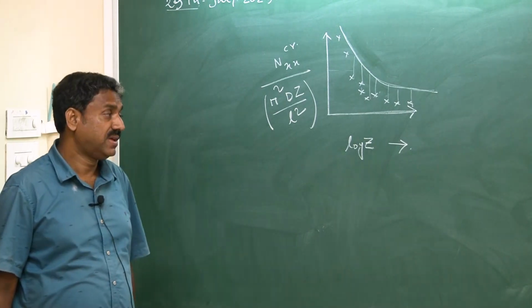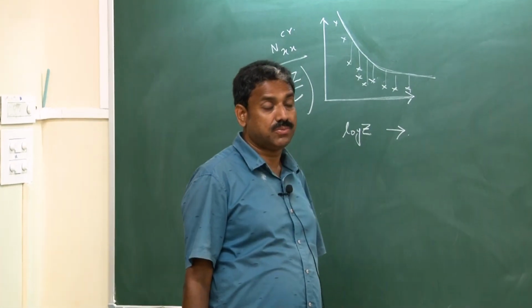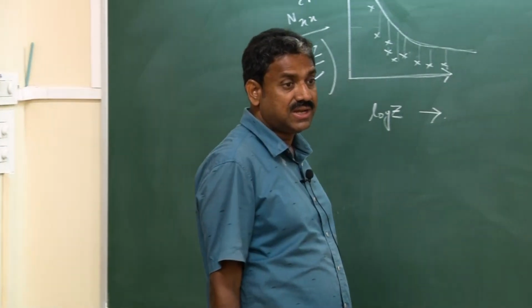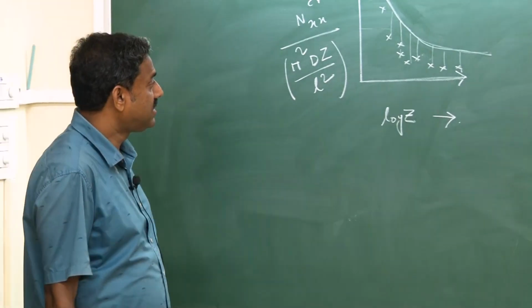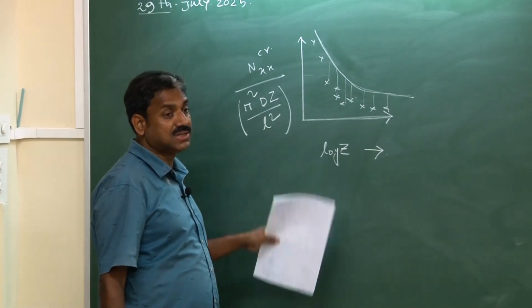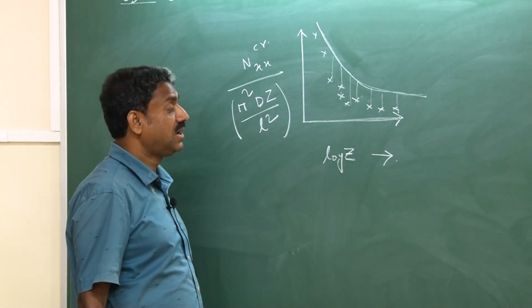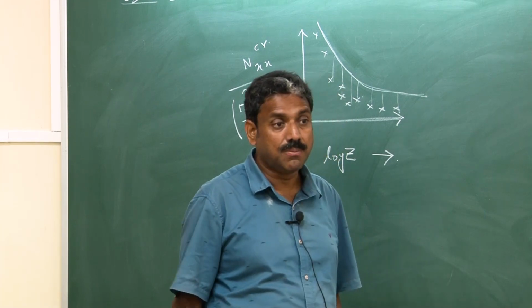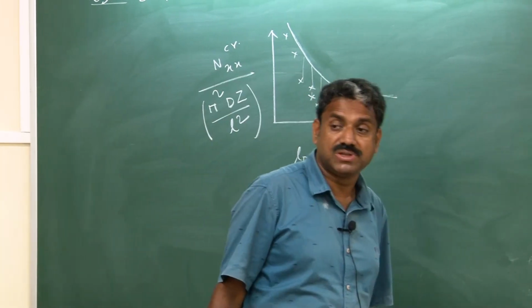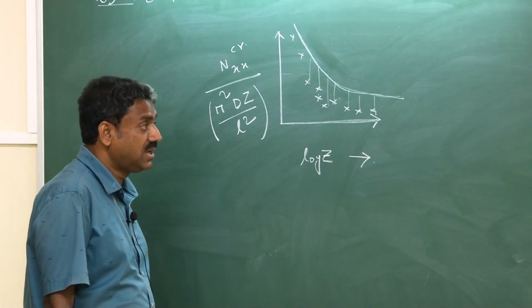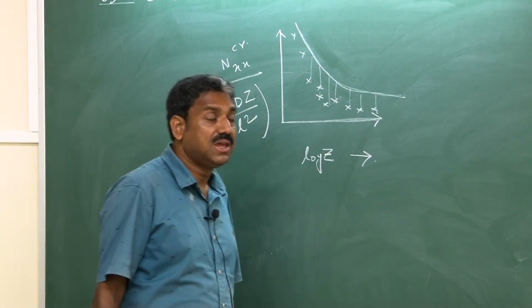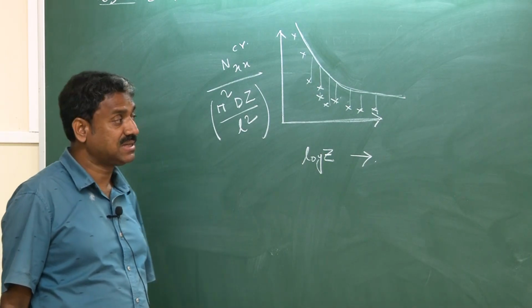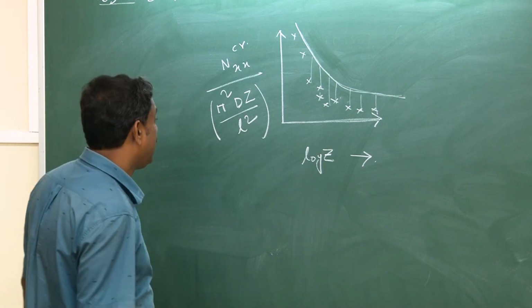Of course, for very short shells, Z less than 2.85 is not quite valid, because that violates the shell assumptions. To summarize, most importantly, it gives you huge reductions in the critical load, because of the multiplicity of closely spaced modes which are coupled through geometric nonlinearity, and then there is an interaction between the modes and that reduces the load. So, modal interaction is a very important thing here.